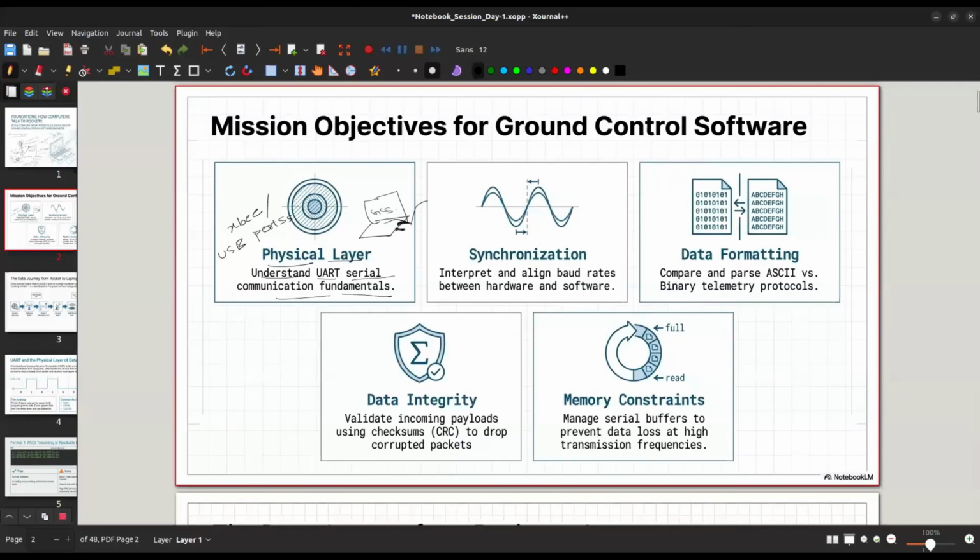Okay, so first you have to take a dummy controller. When I say dummy controller, just take a microcontroller, attach it, and program it this way so that it's going to send you dummy data. Dummy data means data that is exactly in the format of what you're supposed to send from your PCB. So in the same format as the PCB, you have to program your Arduino or any kind of microcontroller that you are using to give you the data, let's say, at a chosen baud rate. And don't worry about these terms, I'm going to explain them in this session.